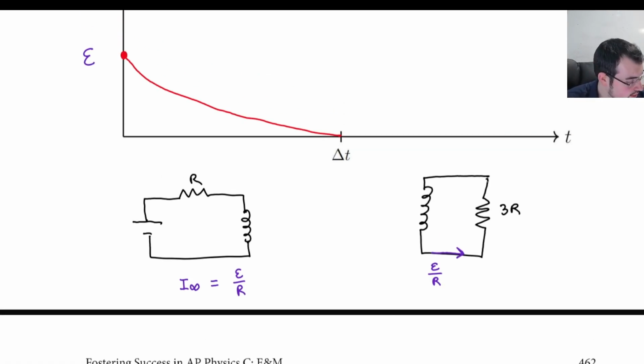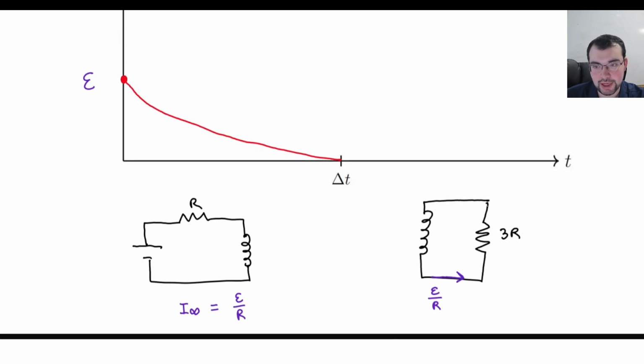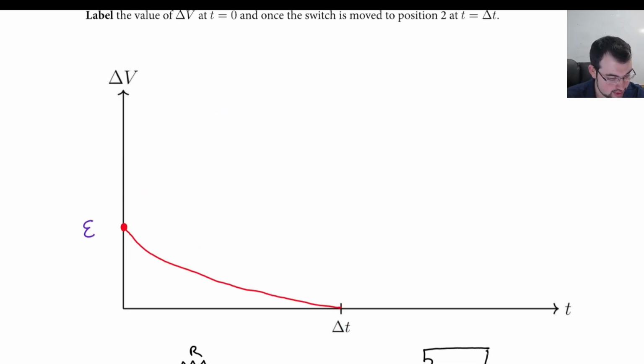And this inductor is wired in parallel with this resistance. So this is that high voltage trick from last time, where we see that you're sending a current through it, and when the resistance increases with that same current, you actually get a bigger voltage drop. So we get a huge voltage spike as soon as we flip that switch over, because inductors maintain the current initially. So we maintain that current through a larger resistance. So instead of it being epsilon, we get 3 epsilons worth of voltage drop at that time. And also, if it really mattered, it would decay slower.